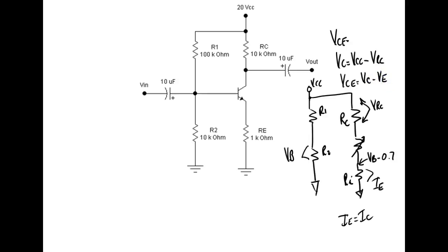And all we're doing is what laws? We're using the laws that you learn in DC. But this looks like a series parallel circuit, or two series circuits that are in parallel, but that's all a series parallel circuit is. Now, most of the time, this is a type of series parallel circuit you run into. In DC, we put some more complex ones, right? We'll put a series resistor here and a parallel branch in the center and then a series resistor. You don't see those very often, but that's just to prove that you can calculate that thing.